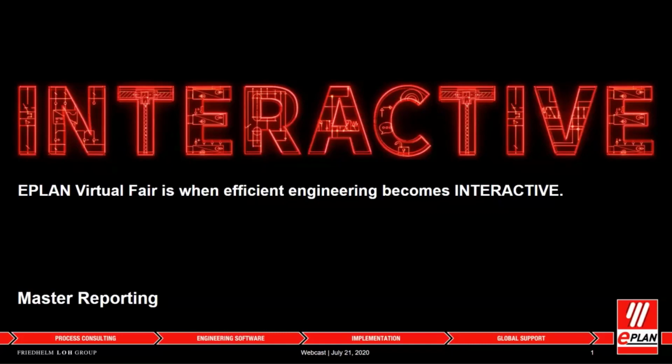The challenge with these reports when working in CAD environments is that all of the data needs to be re-entered or done through a manual takeoff from the schematics into another tool that can list that in a report that can be usable. This is where EPLAN comes in, through the use of a database, because EPLAN is a database-driven system, meaning that we don't work on one page and one file at a time.